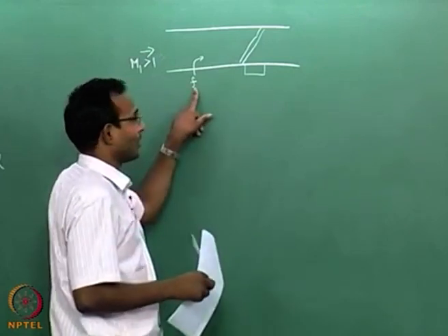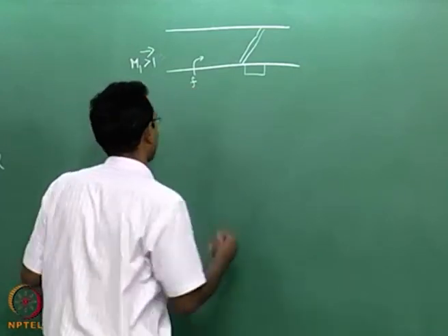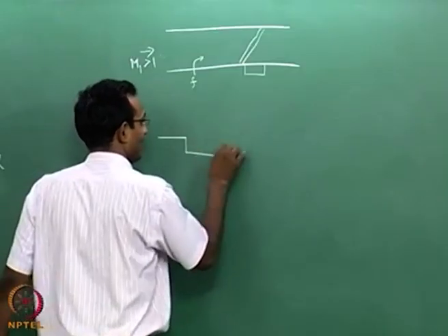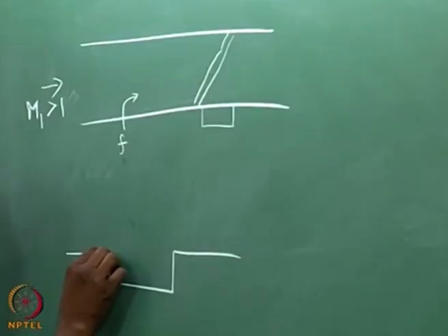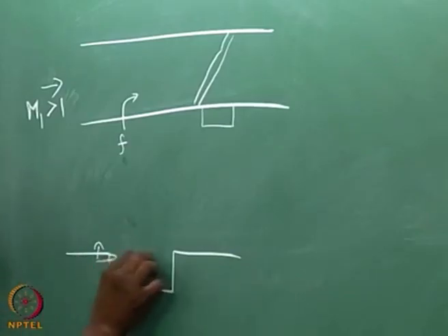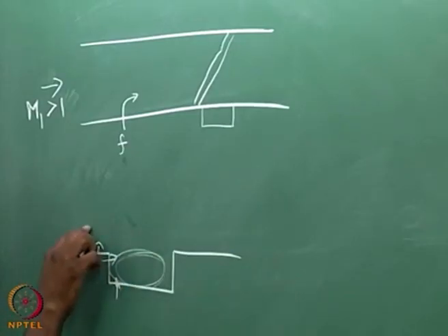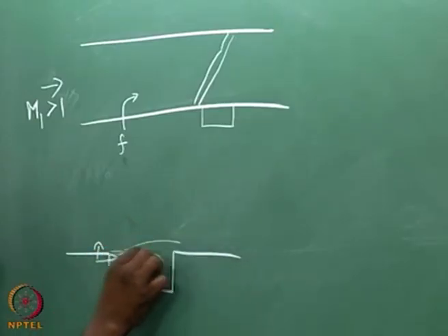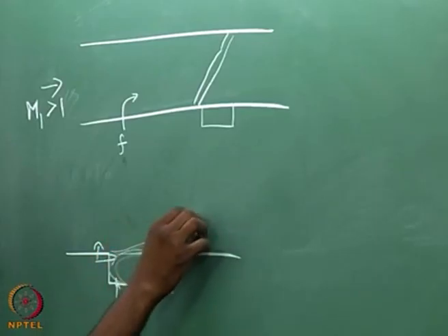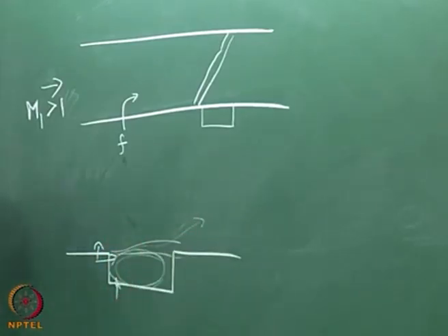People do not inject it always like this, I just gave a typical configuration. People may have a cavity in the wall of the duct and inject it somewhere here or wherever, depending on each configuration, different Mach numbers, it can be any of these places they will inject, and this flow that is recirculating will mix that flow with this fuel and then take it out into this region. There will be a shear layer formed here which will be oscillating, which will send out fuel and air. This is one configuration.